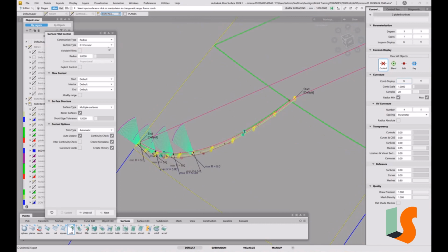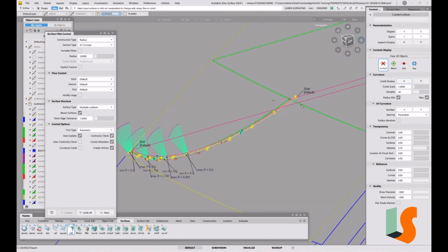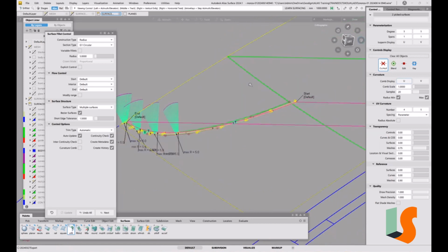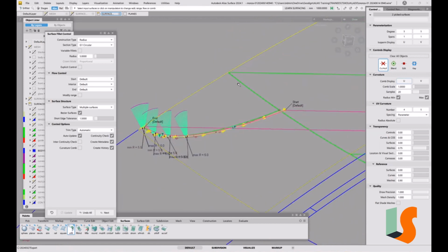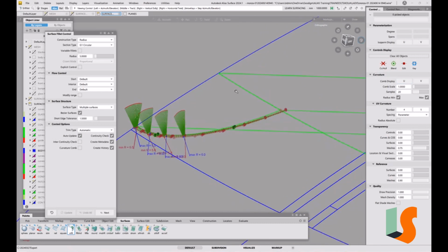When you've got G1 circular fillets everywhere, you might think that it's actually easier to align things, but it's actually more difficult, because when you get into corners especially, it's much more critical than G2, which used to surprise me when I was first learning surfacing. It's one of those things that G2 is actually easier to align than G1 when you get into the corner details and things. So I'm going to use the same fillet size on here, and we'll see what happens, because